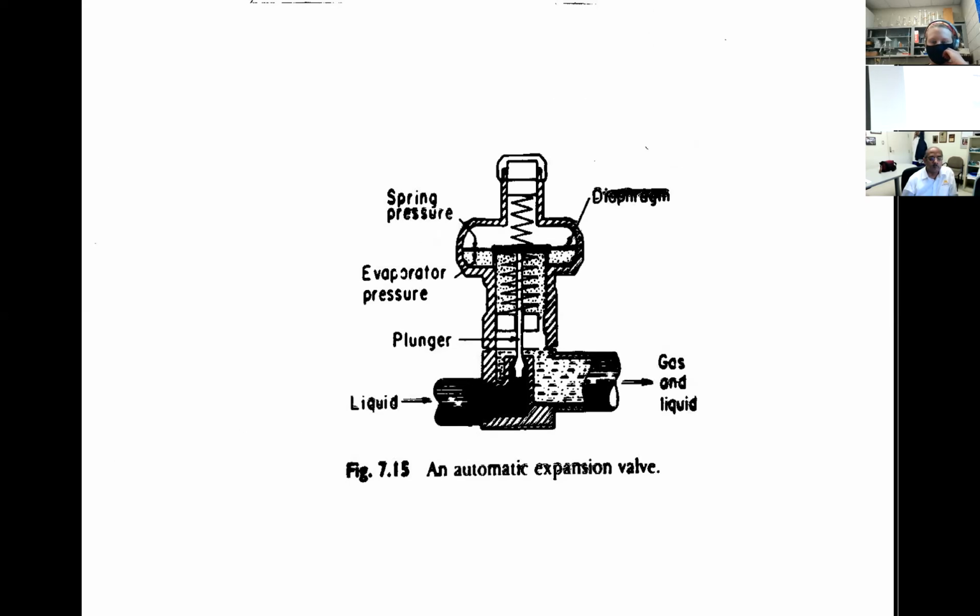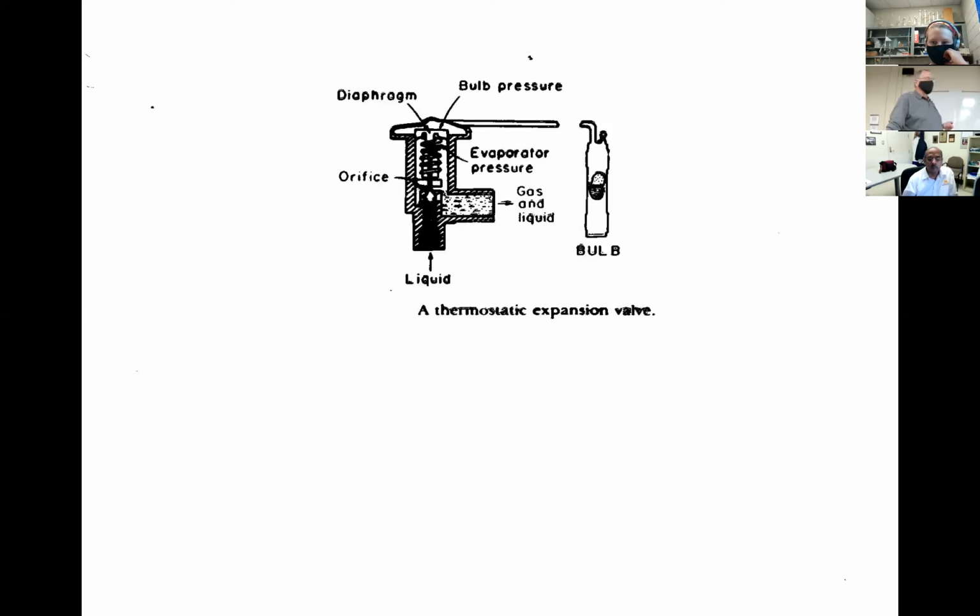There are automatic systems available, so you don't have the float systems. Again, they sense the pressure in the evaporator, since there's less pressure there. It's saying, well, the liquid's been converted to vapor, so it's flowing out, and it allows more of the liquid to flow in and remove the heat. Some are set up thermostatically.